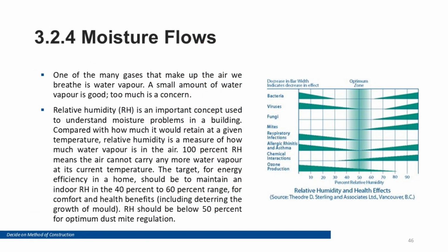Moisture moves as vapor and as liquid water. Vapor often travels with air leakage, while liquid water can move via capillary action through porous materials. Effective construction uses drainage, flashing, capillary breaks, and moisture control layers, so assemblies stay dry and insulation remains effective.